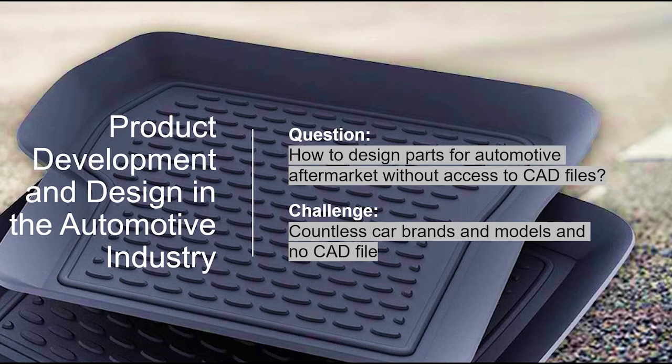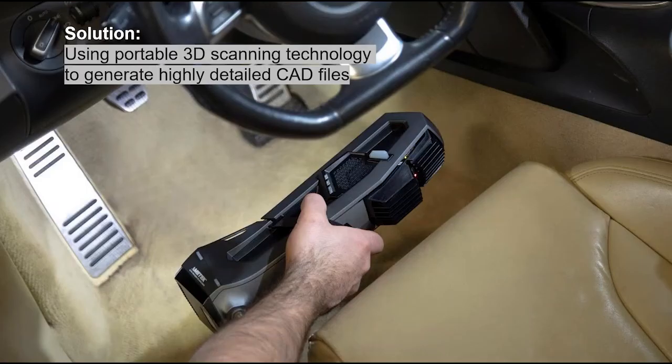Well, the challenge here in this product development is the multitude of car brands and models available on the market, which are also renewed every few years. Each car model requires a custom design, and measurements must be taken quickly on complex surfaces. This development must be also done very quickly to be the first on the market. So the solution is to use a portable 3D scanner to quickly capture these complex surfaces within a few minutes. This can be done anywhere as it requires a very limited setup time and acquisition time.